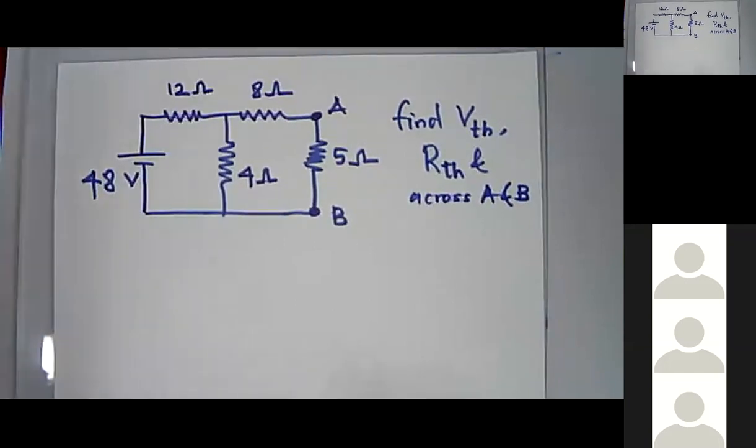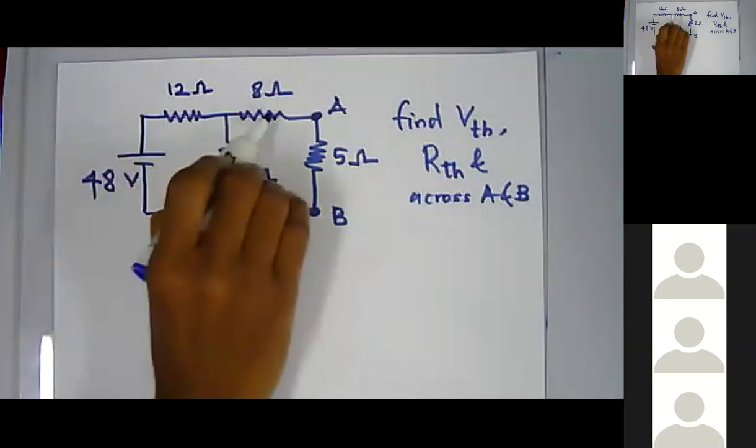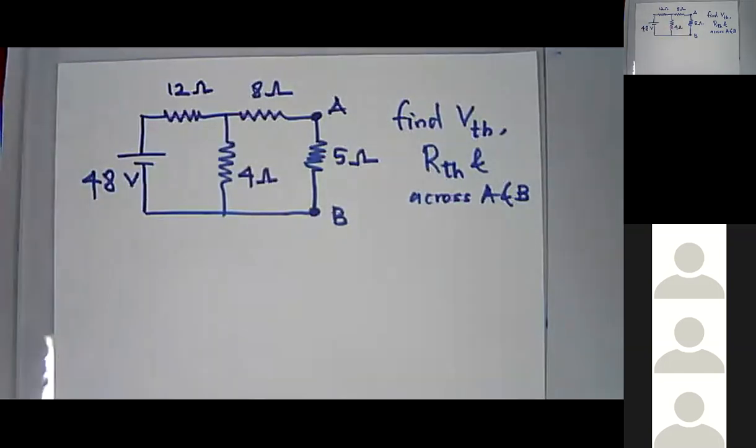Now what Thevenin's theorem says is that you can reduce any complicated circuit to a simplified circuit with an equivalent battery and a single resistance, but the circuit must have only linear elements, which means you must have only resistors and batteries in your circuit. If there are any non-linear elements, then you cannot apply Norton's or Thevenin's theorem, right?